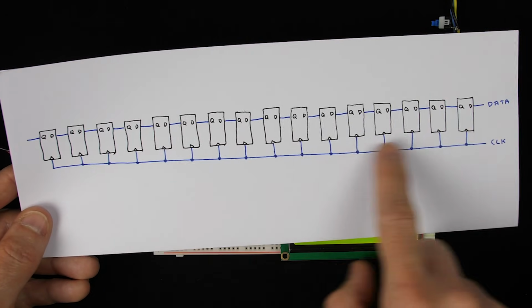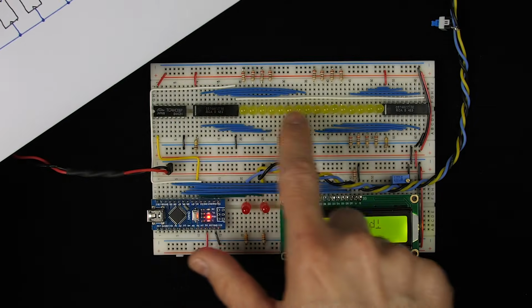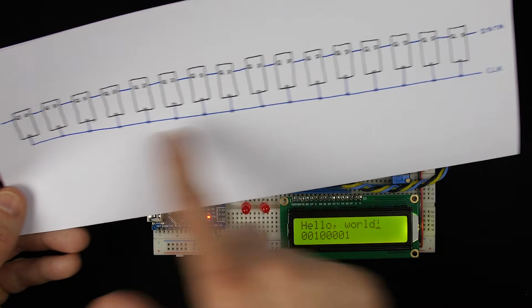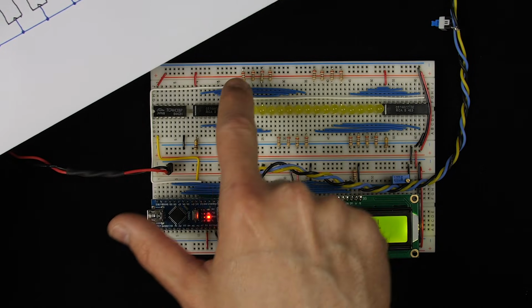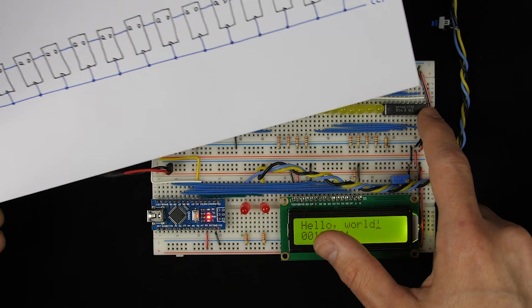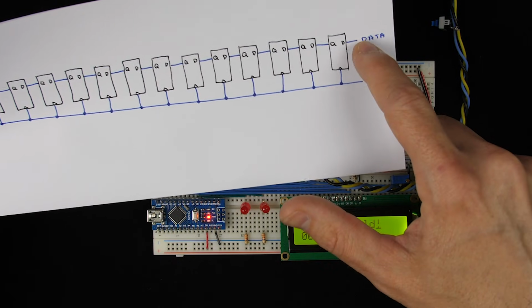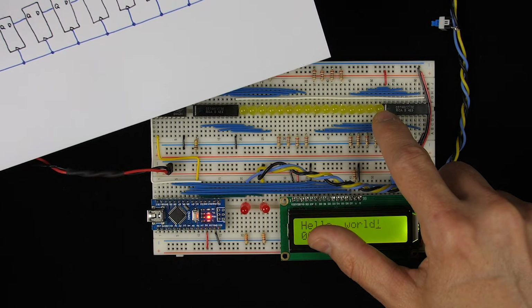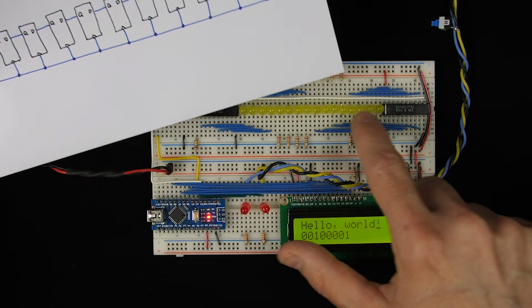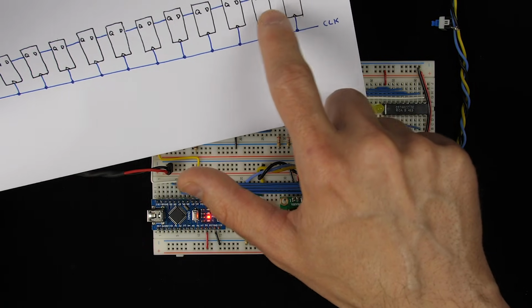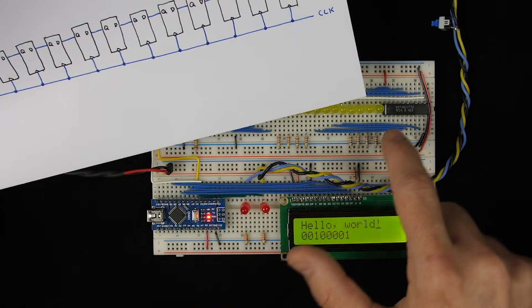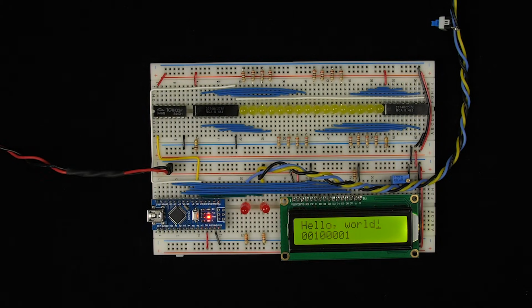Okay, so we've got our 16 D flip-flops here, and they're hooked up to LEDs so we can see what's in them. And we've even got our clock hooked up. That's this white wire that's hooked around here. And so now what we need to do is hook our data into one of them. I guess we'll do the one on the right here, just so everything kind of makes sense. And then hook the outputs of each one into the inputs of the next one. So that's what I'll do next, is just hook up all those outputs and inputs.